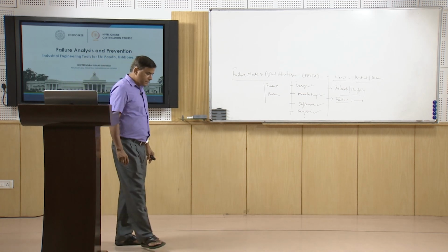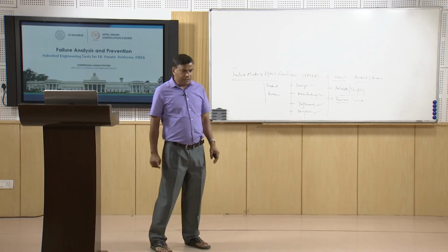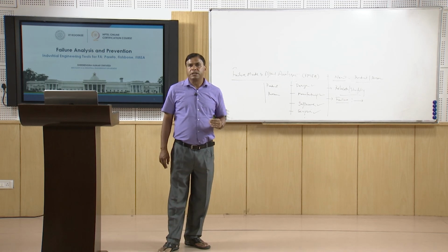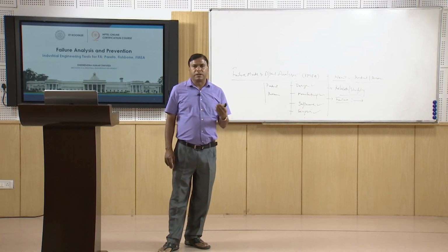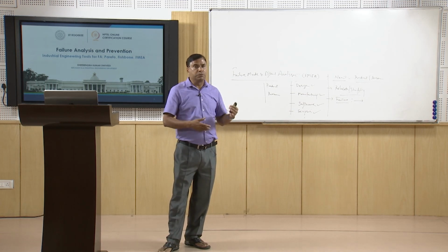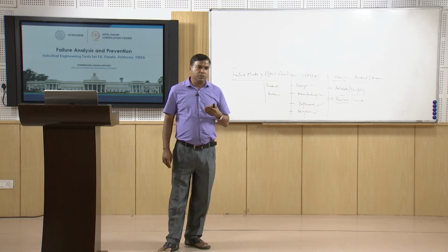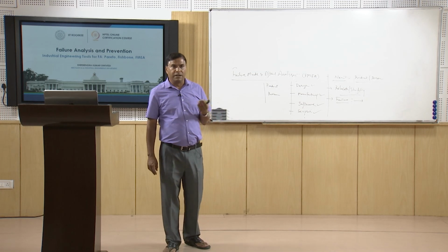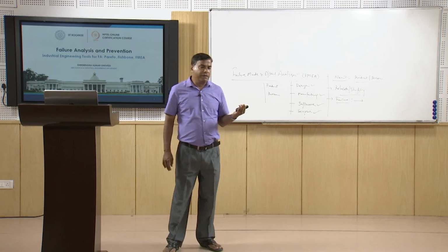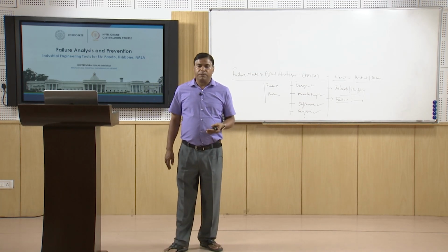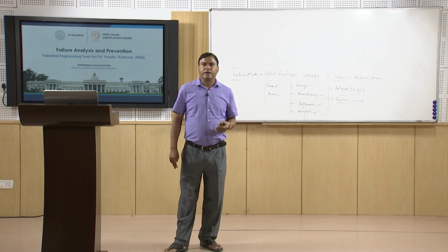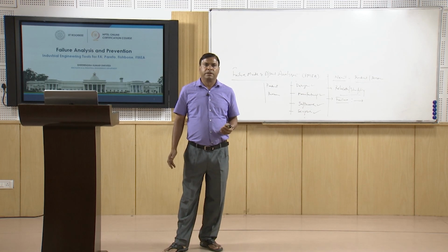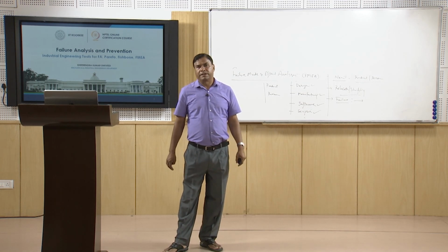And now I will summarize this presentation. In this presentation, I have talked about the Ishikawa diagram to see what are the major causes and what are the minor causes, and how to build up those major and minor causes to identify the things that need attention to avoid the failure tendency, and to have the particular kind of favorable or unfavorable effect. And similarly, I have also talked a little bit about the failure mode effect analysis.